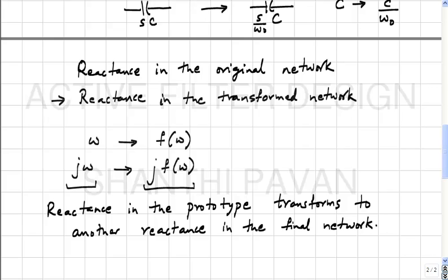Two, we saw in the network synthesis part that if the LC network is lossless and if it's equally terminated on both sides, then the sensitivity of the realized transfer function to variations in inductors and capacitors is low. You've all done the Monte Carlo stuff, right? And you've seen for yourself that it is indeed true, right? Because the magnitude of the reflection coefficient cannot physically go below 0.